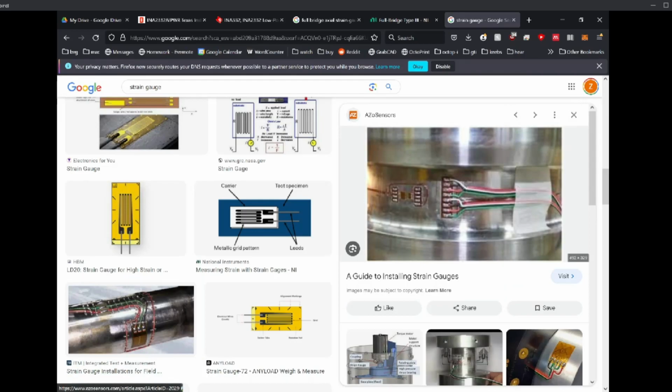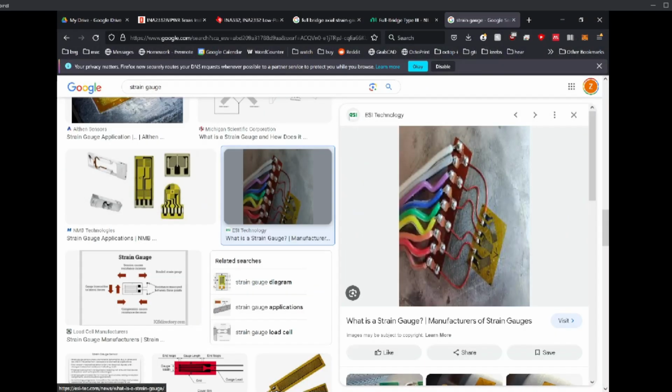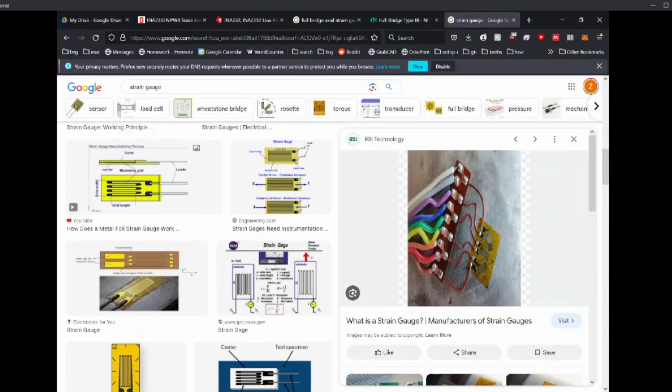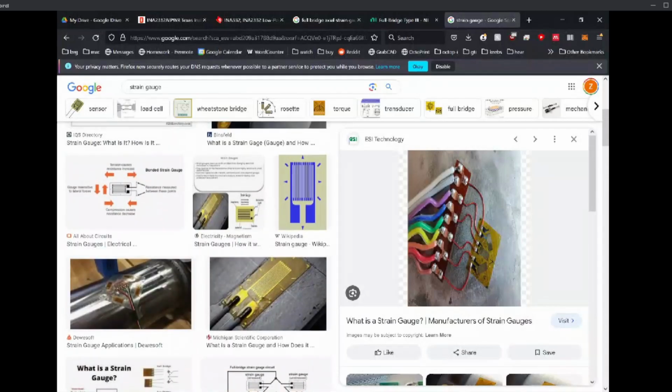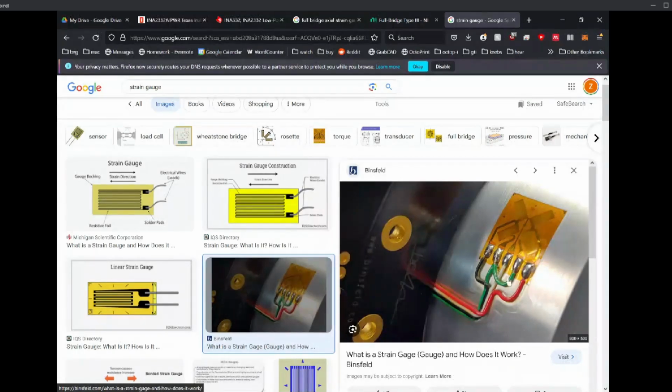Maybe this is a good picture if it wasn't such bad quality. Oh, here. That's a good picture. Yeah, this is actually exactly what it looks like most of the time, except it's not more than one connector. It's just one piece of copper, just like this. But you CA glue this whole row down, and then you solder your strain gauge wires to it on one side, and then the Wheatstone bridge wires on the other side. And this also lets you, like we saw in that first picture, create your bridge just using wires on this pad. In fact, I was doing that the other day. I actually did something just like this guy, with this green wire bridge in between 2 pads. Makes it super easy.